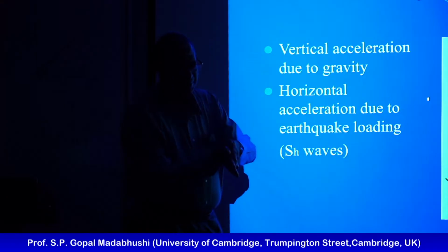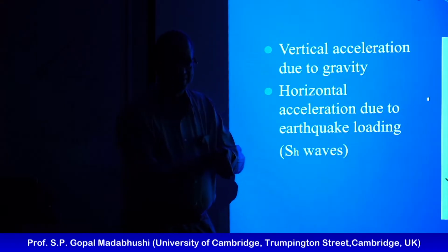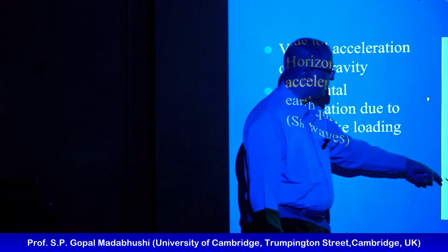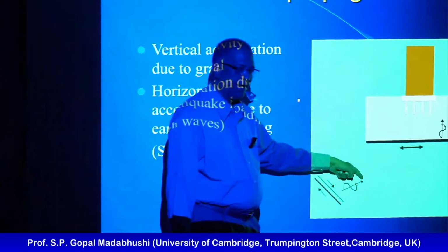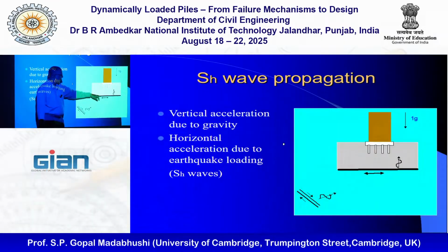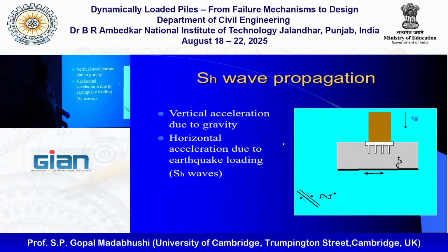So that slip and the following elastic oscillations are what we see as vibrations. Those travel very quickly through the bedrock, because bedrock is quite solid. Every point along the base will see these vibrations, and every point will then start to shake the soil in that direction, and you get the propagation upwards. These are called horizontally polarized shear waves, or SH waves.